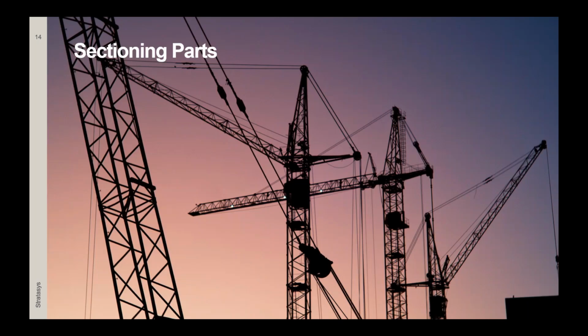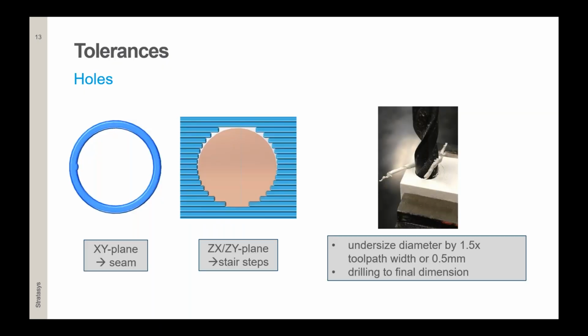Very good, Carolus. We got one question, and that's regarding the best practice for printing holes. If I have a choice, would I print my holes horizontally or vertically? Well, I would say if you have a chance, normally geometry might be different, but if you have a chance to influence where the holes will be positioned or how they would be printed, I would recommend, from my personal experience, to print them horizontally.